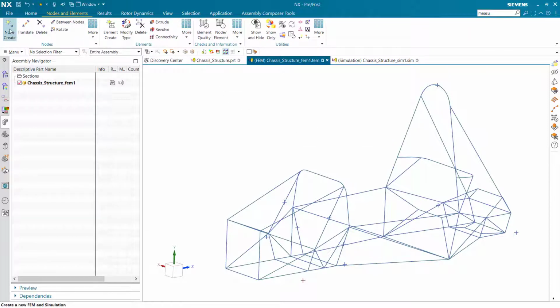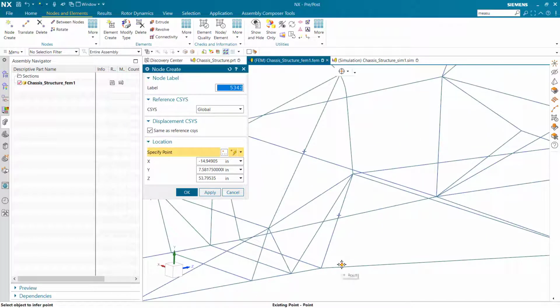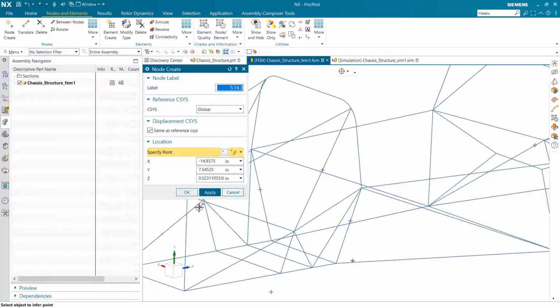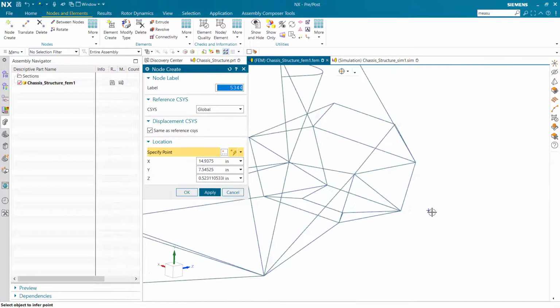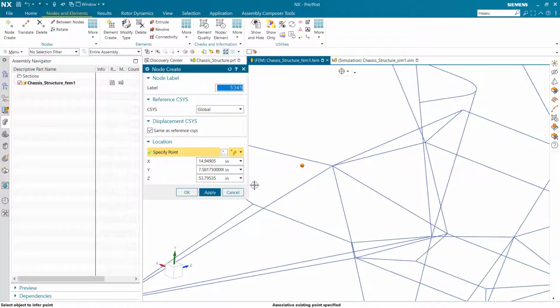The only thing we need to do is create additional nodes to apply our constraints and loads to, as well as connector nodes to connect where we're applying those forces and constraints to the chassis itself. To do this, I'm going to create 4 nodes, which will essentially act as the center of mass for the tires, and create 1D connection nodes to connect that point to the chassis, where the 4 suspension struts would be placed.